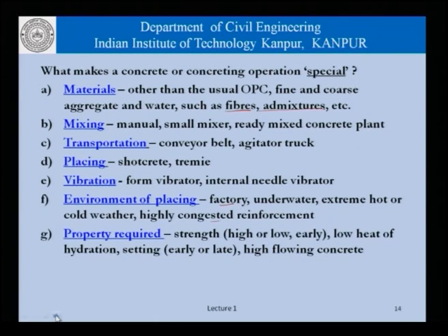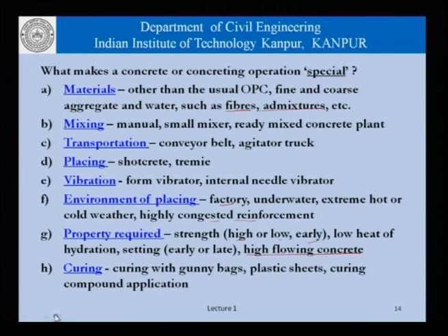The property that we require for concrete, we may require high strength or low strength, we may sometimes require early strength, which is especially the case, for example, in a repair project. We may require a low heat of hydration, which is the case in case of a mass concrete project, and so on. Sometimes we use high flowing concrete when the reinforcement is very congested, as we shall see in this course. Curing conditions, gunny bags, plastic sheets, curing compounds, and so on. So the point is that once any of these conditions or any of these processes goes out of a normal range, we would call the concrete and the concreting operation as special.